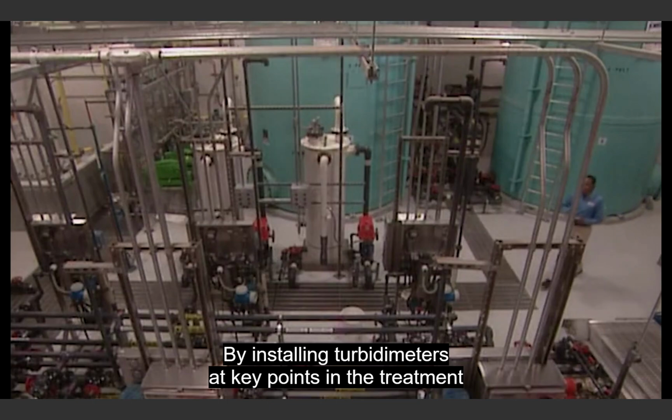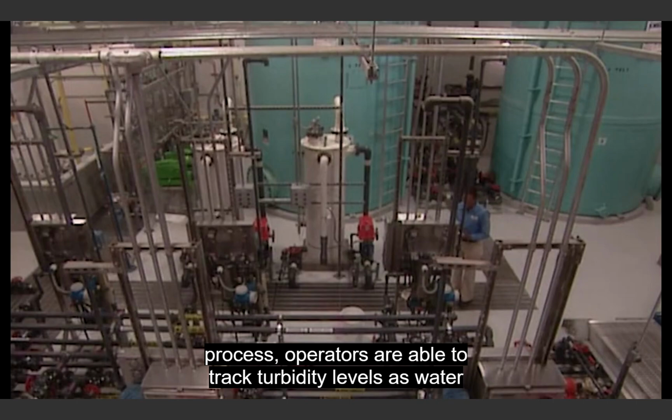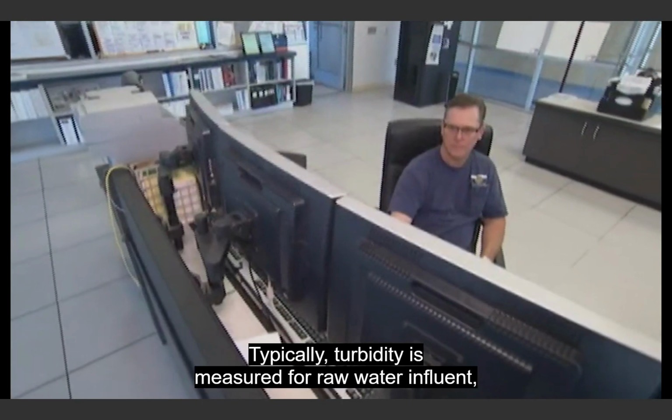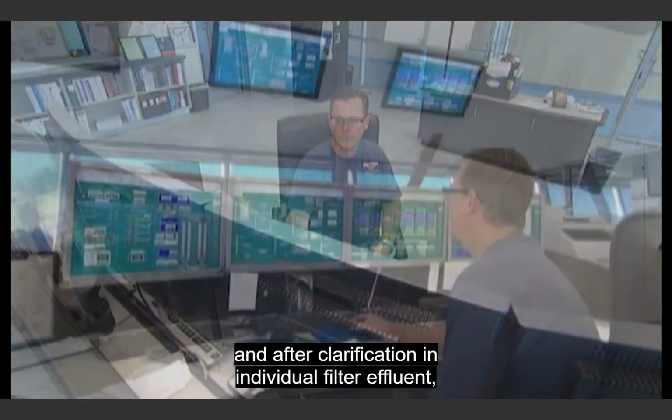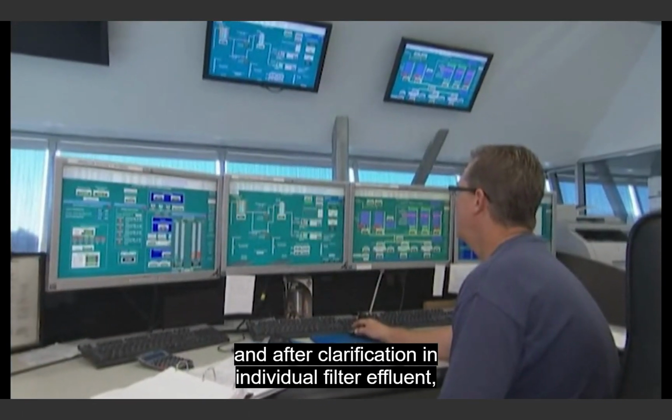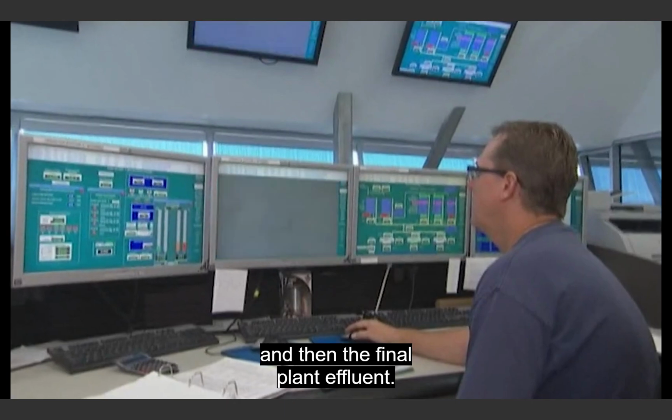By installing turbidimeters at key points in the treatment process, operators are able to track turbidity levels as water moves through the plant. Typically, turbidity is measured for raw water influent and after clarification, in individual filter effluent, and then the final plant effluent.